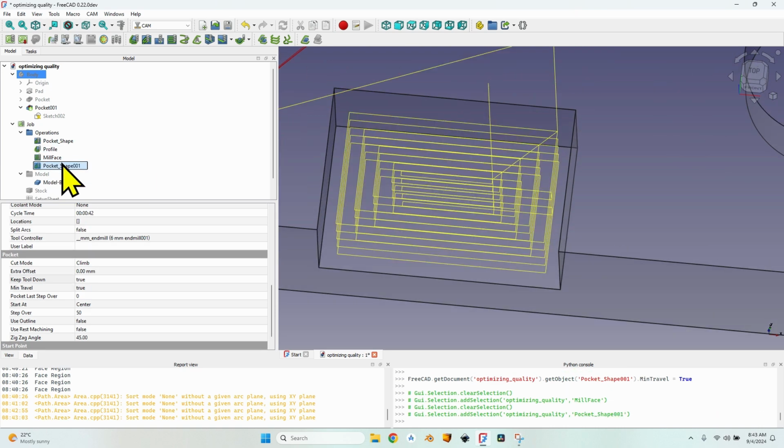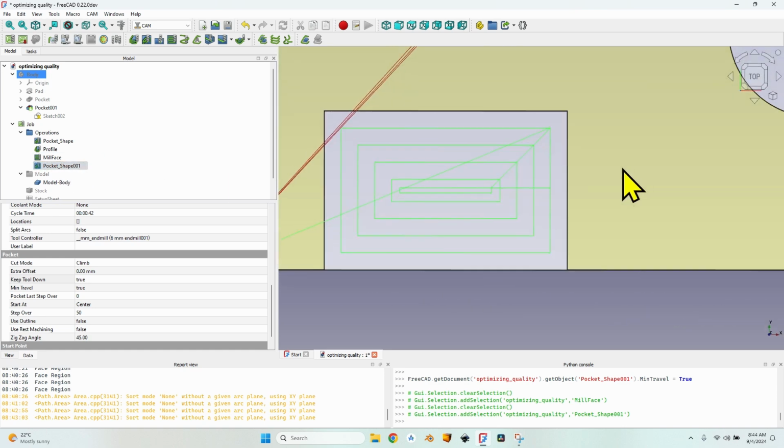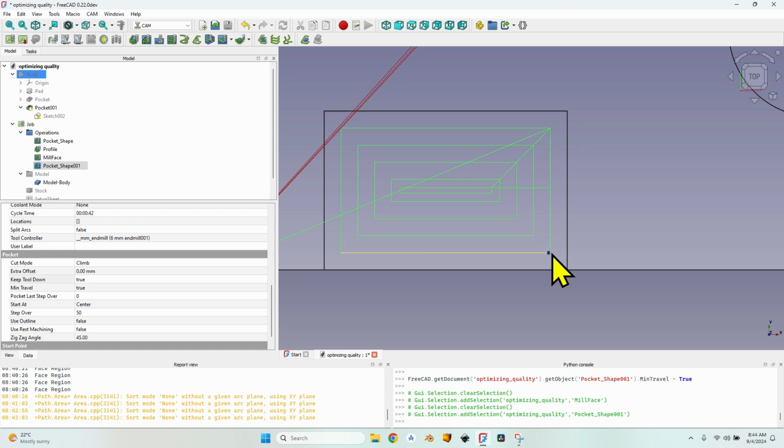If I want smoother finish, of course I can make the same thing that I did earlier with the other pocket. I'm not going to do it now, but I'm going to show you something that is very important. If I set a top view, you can see that the cutter head will stop here. If you imagine a round cutter head here, you will realize that you will have a small round over at the end of the pocket, which is something that of course you don't want.